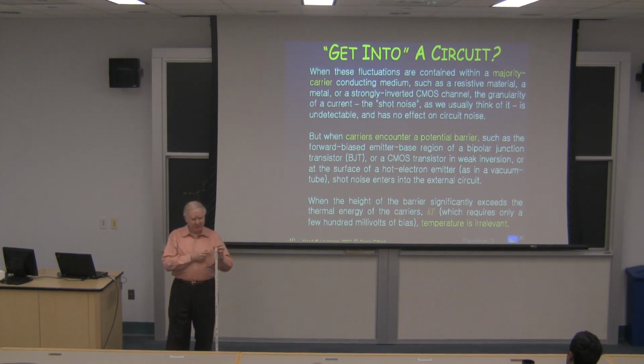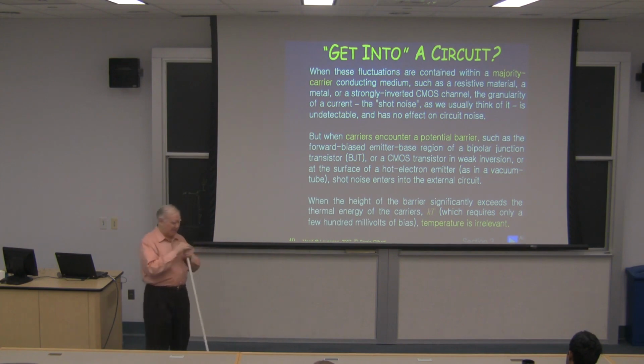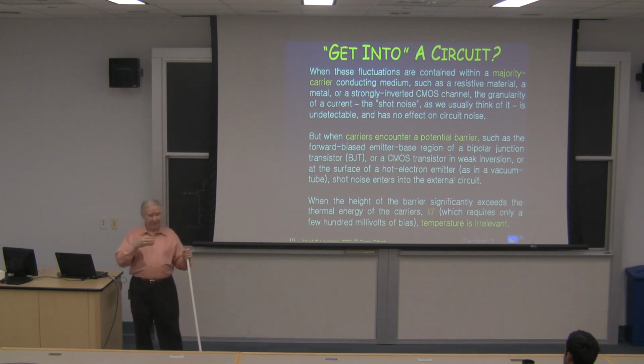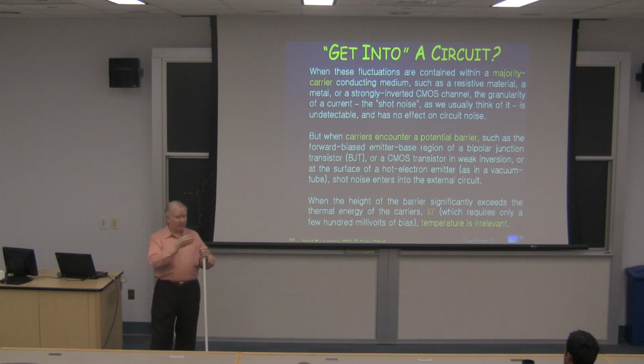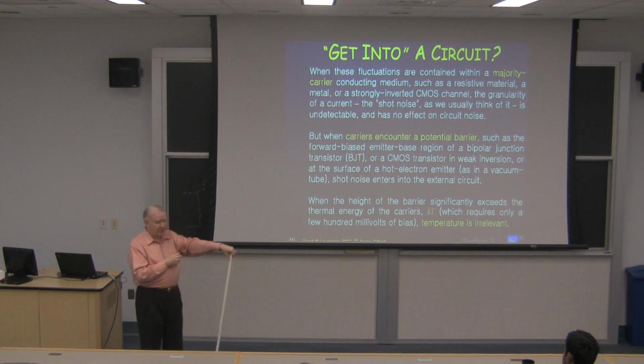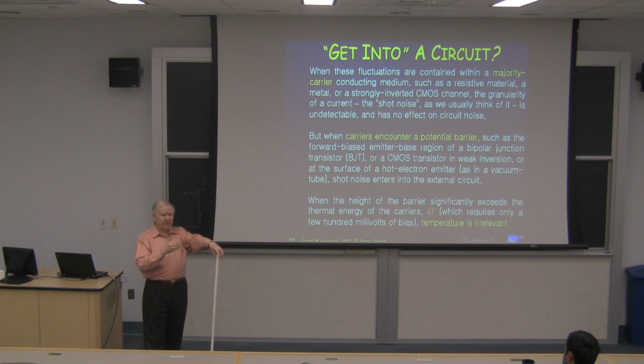Shot noise is not going to manifest itself quite so evidently, again, these two overlap so much I have to be careful what I say, but in a field effect device where all the conduction is by drift, with a majority carrier as the predominant carrier current, it's essentially resistor noise. There's no shot noise associated with that. So a field effect device does not suffer from shot noise in the way that a junction device does, where a potential barrier is a place where we can actually count and watch the passage of electrons or carriers.